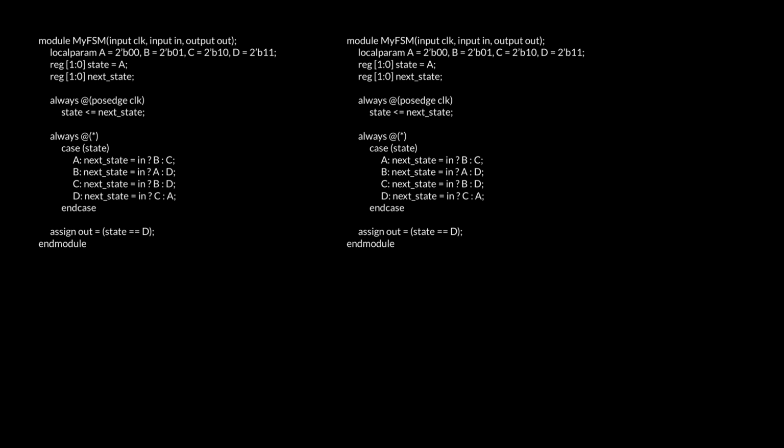We will look at how to eliminate the possibility of having a glitch in the output of a Moore finite state machine by eliminating the output logic. You're not seeing double. This is going to be my original finite state machine that I will leave unmodified, and over here we are going to modify it so that we eliminate the output logic, which means that there won't be any glitches. The output's just going to be a direct function of the state. No need to have any logic gates there.